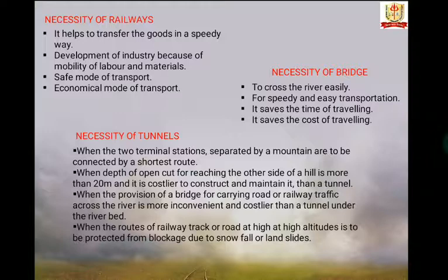Necessity of tunnel. When two terminal stations separated by a mountain are to be connected by the shortest route. When the depth of open cut for reaching the other side of a hill is more than 20 meters and it is costlier to construct and maintain than a tunnel.